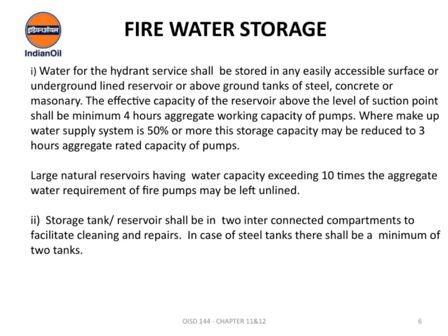Let's talk about water storage for hydrant service. The water should be stored in easily accessible reservoirs, which can be surface, underground lined, or above ground tanks made of steel, concrete, or masonry. The key point here is that the capacity of these reservoirs, above the level of the suction point, must be at least enough to support 4 hours of the pump's combined working capacity.